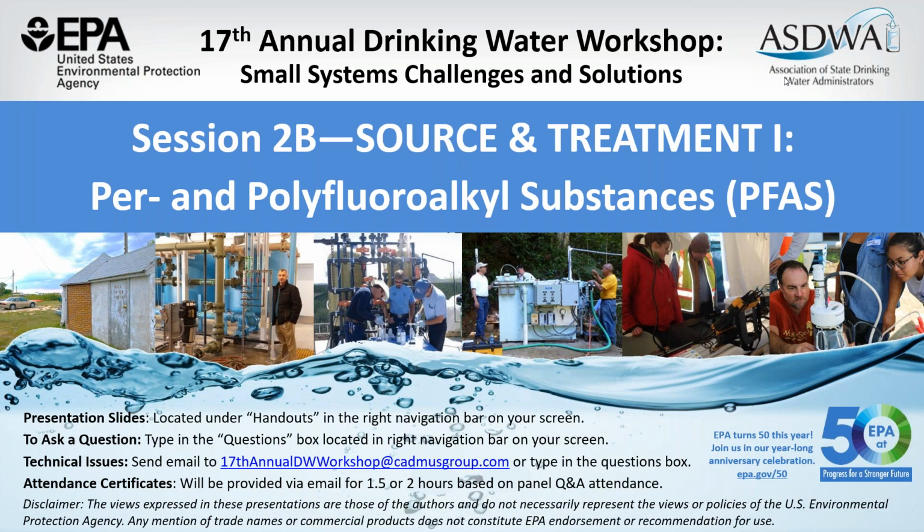I think the questions are directed to me on my study. We'd asked the utilities to try to pair their source water coming in and their treated drinking water coming out. So we're looking at the same parcel, but they may not have done that as well. Additionally, there is some work looking at precursors that might be forming the PFAS compounds during treatment. I think maybe more on the wastewater side than the drinking water side, but still it's possible. But we did not monitor for any of those precursors, so we can't say one way or the other if there was conversion or production during treatment. So we're really not sure why exactly in some cases the effluent was higher than the influent in our locations.